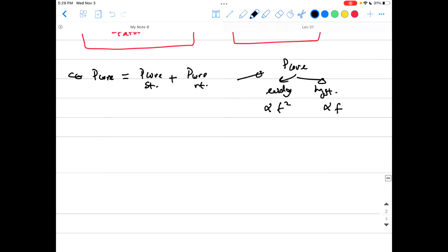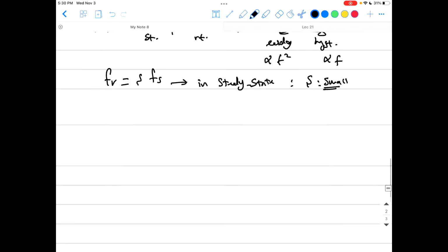And I hope you remember this, the frequency of the rotor circuits equals the slip times the stator frequency, okay? And in steady state, where the motor has reached its steady state speed and it's now working in a stable state, the slip, guys, is a very small value. That's for you to know. So the mechanical speed, which we said before, is less than the synchronous speed, but by a small amount.